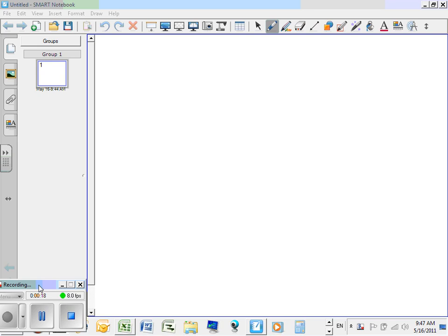There you go. If you guys look at item number 3, it says PTW. We need to print for PTW. We need to print 11 by 17 one-line diagram. I'm going to show you how. Short circuit report, input report, load flow report, and a bunch of coordination curves.